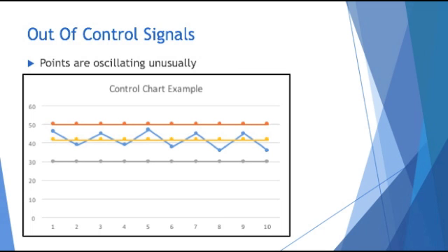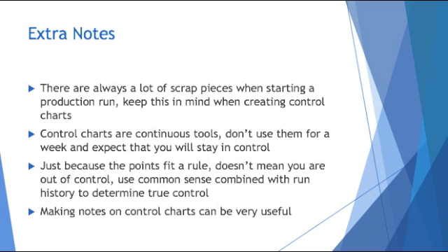And no one would know that unless you had some sort of data that showed, hey, our 2 machines are producing at different levels. A control chart would be one way to catch this. Just like the example shown here. This might be 2 different machines working together. So all the examples I just showed are reasons why control charts are great. If I had just showed you the tables of numerical data, you probably wouldn't be able to spot the out of control points. And you probably wouldn't be able to notice trends, at least not right away. That is what is so great about control charts.